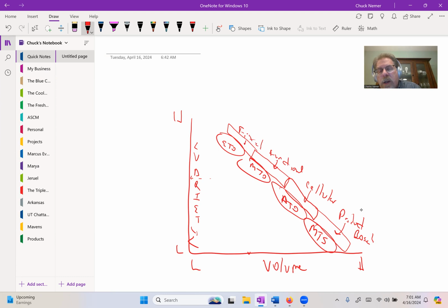So what we mean here on the very bottom right by product-based layout for our manufacturing layout is we're setting up an assembly line for the product. So we're taking one machine from work center A, one from work center B, one from C, one from D. We're setting up an assembly line that's based around the product. So this could be like making pens or cups or paper clips or any product that's high volume, low variety.